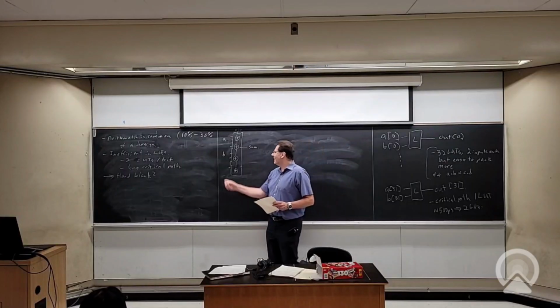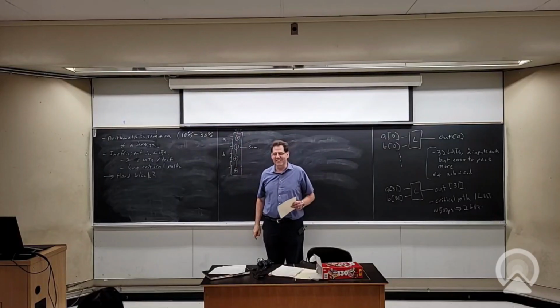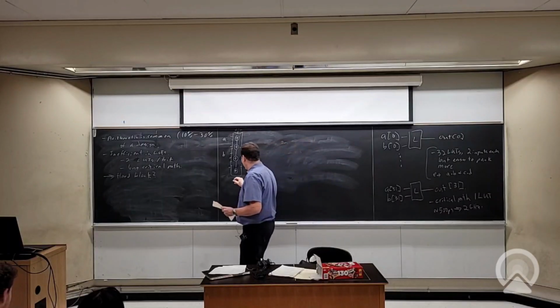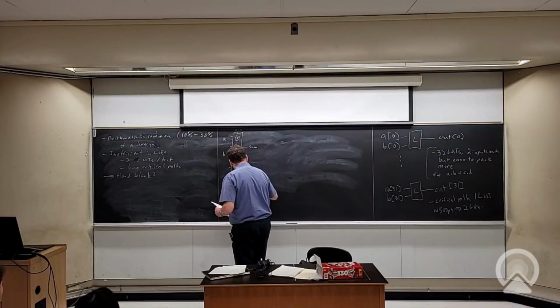Okay, so I got LUTs. My LUTs are going to complement this, and I'm going to make C in. I'll give you a subtractor. Problem solved. We now have an adder, but it is a good idea. We want to make hard blocks as flexible as we can. This is no longer my adder. This is my adder/subtractor. So that actually would be a better design.